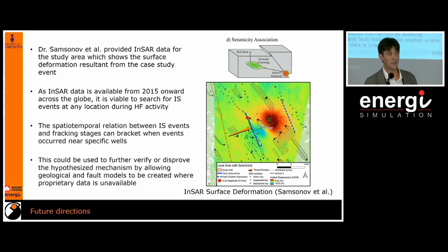And when you look at InSAR data at the well during the injection, you can see an uplift, and the uplift is actually quite large, about 2 centimeters over an areal extent of a couple of kilometers in diameter, a little bit more. So definitely you were opening bedding planes during that completion.